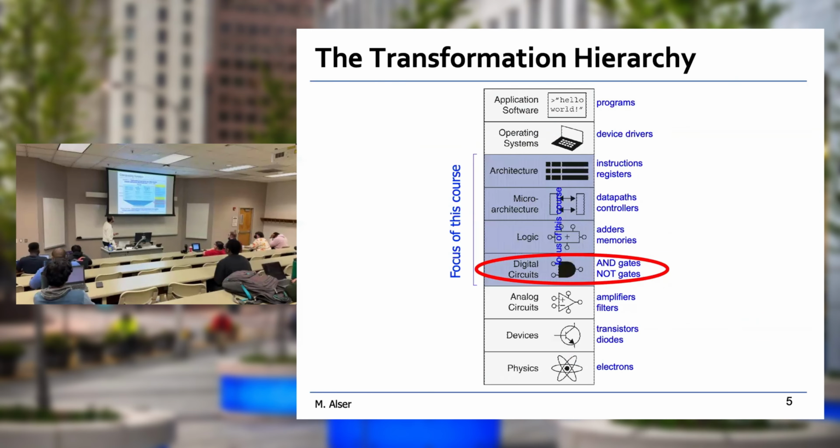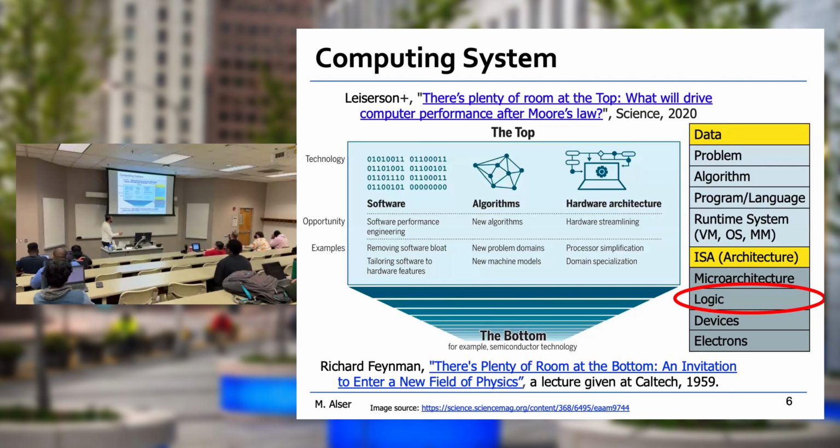All right? So we're still in the compute stack, in the logic layer, which is an extremely important layer where we do all the calculation at the transistor level. Although we simplify the view, we don't see the transistors, but we see gates. And a gate is an abstraction view of the transistors. Every gate is built on top of a couple of transistors, as we saw in lecture 4, I guess, where we implement the NOT using 2 transistors, for example, right? We implement the NAND using 4 transistors, and so on. So each of those gates is really an abstraction view of those transistors.